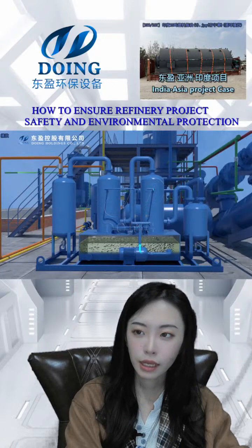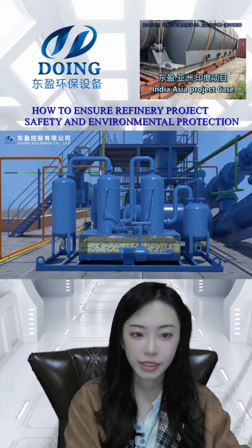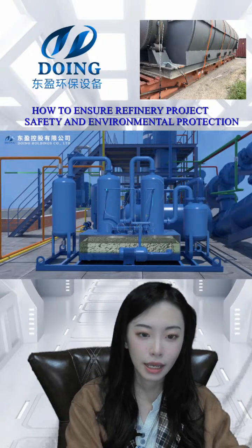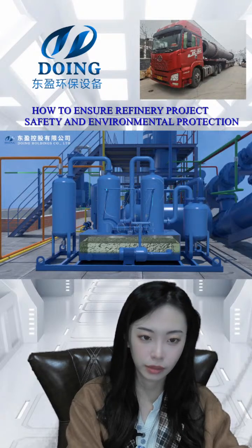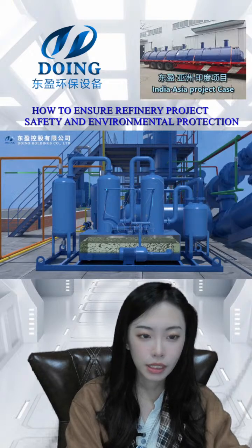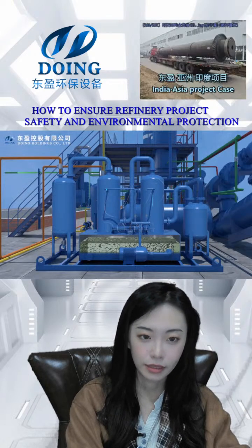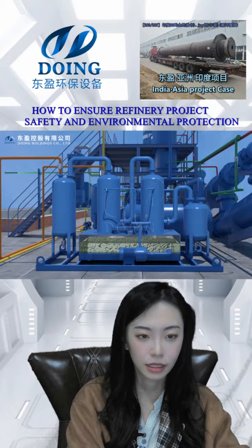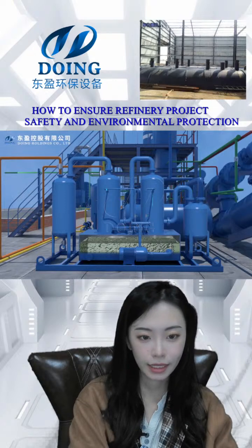Okay, and let's look at this. This is the optional environmental protection device. It's called the tail gas odor removal system, or the desulfurization system. The circulating water containing sodium hydroxide reacts with the tail gas in order to remove the hydrogen sulfide inside.